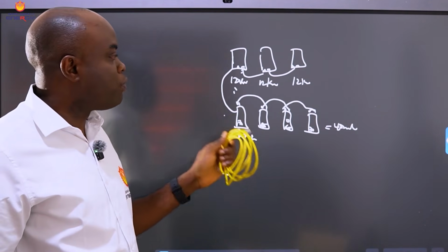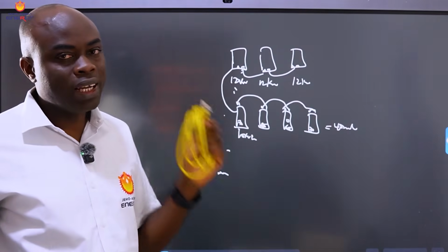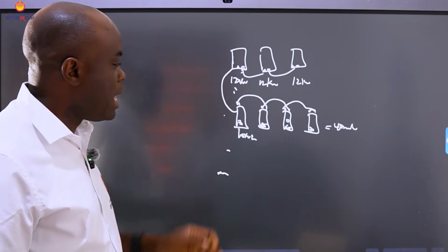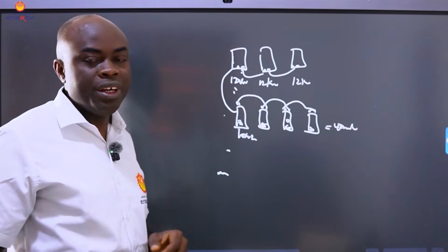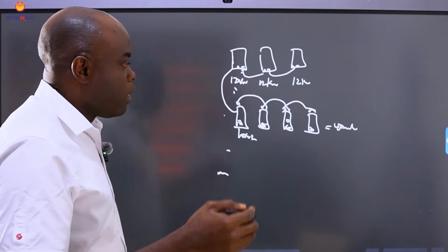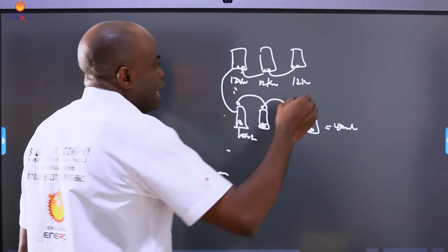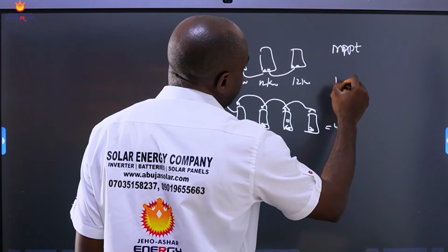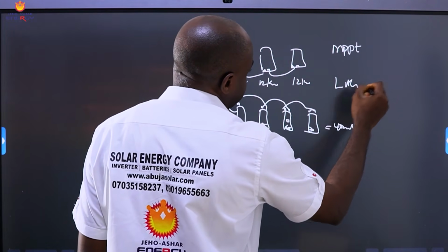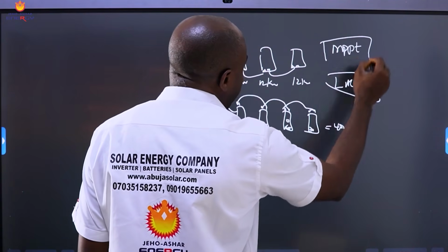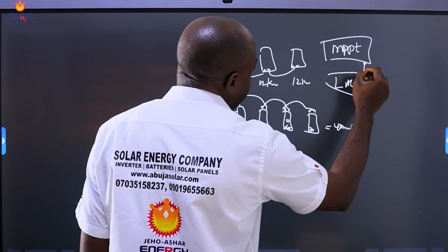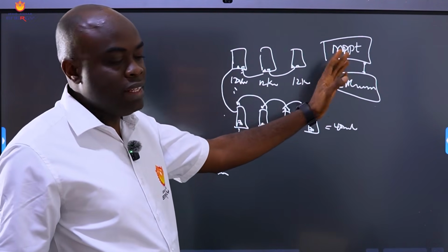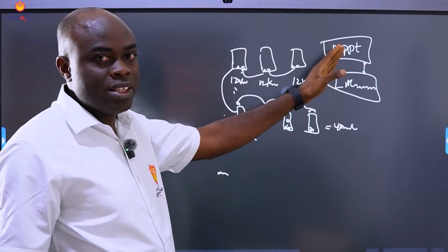So the presence of a communication cable, CAN RS485 communication cable, in your solar system, that is the inverter and battery, is very important. Also, for those of us that use MPPT to charge our lithium battery, and we don't have a communication cable in between both of them, we are doing our customer a disservice, right?